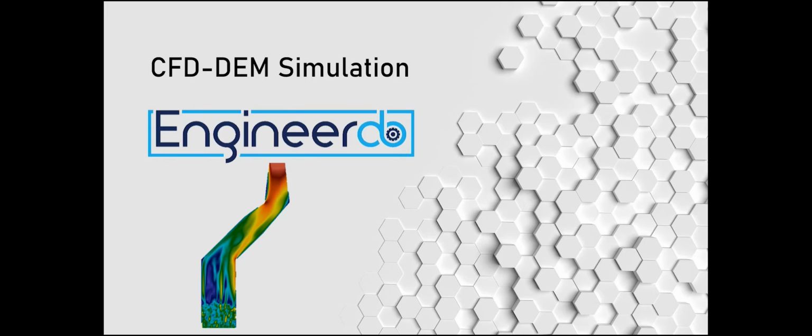Okay, let's get started. Since this tutorial is more detailed and will show how you can set up a simulation based on a model which is similar but different, I will use the fluidized bed simulation that you can download from our website in the link below, and I will modify it to the structure which is shown under this logo here. The bottom of the structure will be filled with particles, and after the particles are settled, I will push air through the column of particles. This could be a reaction process where particles are streamed through by a gas stream.